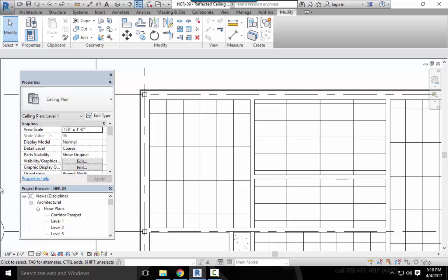Well, the book says it wants it because it's showing you that it can be done. Doesn't mean it's necessarily a proper thing to do. Remember when we said earlier in the semester that this building is not a really well-designed building? It's a building designed to show you all the different things that Revit could possibly do. So yes, you could rotate that just like the book shows. But I can't see a good reason for doing it in the real world. So I'm telling you, just because you can do it, and Revit has the ability to do it, doesn't mean that you don't still have to think about the real world constraints when you're laying out your ceiling.